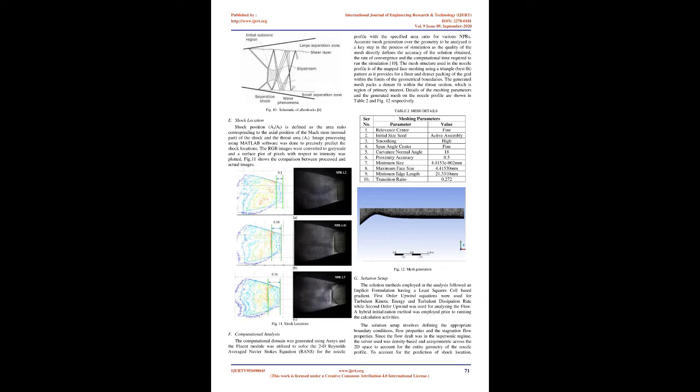The shape of the Mach disk is determined by the non-uniformity associated with the flow upstream of the separation shock. The non-uniformities are governed by the presence of both axial pressure gradients and radial pressure gradients in the upstream flow. For supersonic nozzle flow, the axial gradient can be positive or negative. For the shock structure shown in Fig 8, the Mach disk BC is convex in shape. This can be attributed to the type of pressure gradient present in region 1. Such a pressure gradient increases from the nozzle wall towards the nozzle axis, i.e., pressure P increases from A towards the nozzle axis. The Mach number and shock strength also follow the same nature. Similar variation with respect to pressure gradient and Mach number can be observed in the subsonic flow in region 2. Fig 8. Convex-shaped Mach disk.